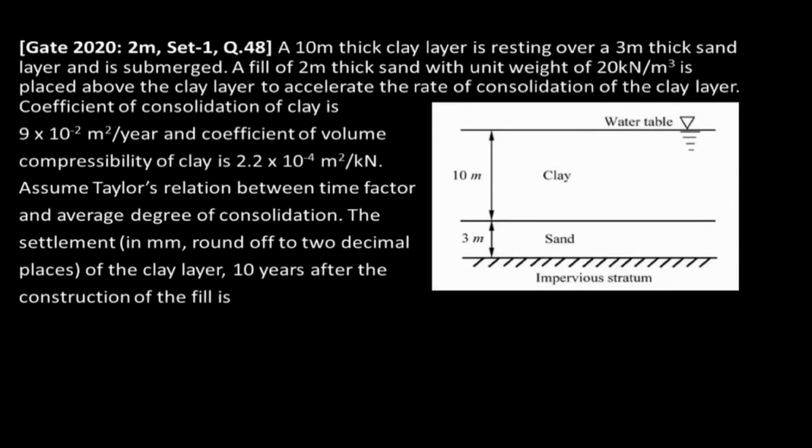If you see this question, they have given that a 10-meter thick clay layer is resting over a 3-meter sand layer and it is in submerged condition. Also, they have given that 2-meter thick sand with unit weight 20 kilonewton per meter cube is placed above the clay layer to accelerate the rate of consolidation of the clay layer.